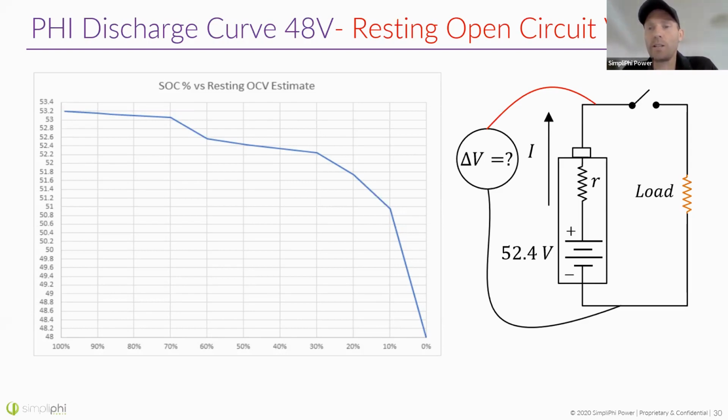So we had the discussion recently, right? Whether or not you need it with an Amplify battery, the reason you might want to add it is that the batteries might be cold in a low temperature environment early in the morning, but your charging is there early in the morning from solar. So if you want to start your charging cycle early in the day off of solar, you would want to add a heating pad or at least an insulated cabinet, so that as soon as the solar is there, your batteries can start charging at quick rates and you're using as much of your solar as possible. They're very well tested. We sell a lot of these heating pads and very rarely have them come back.